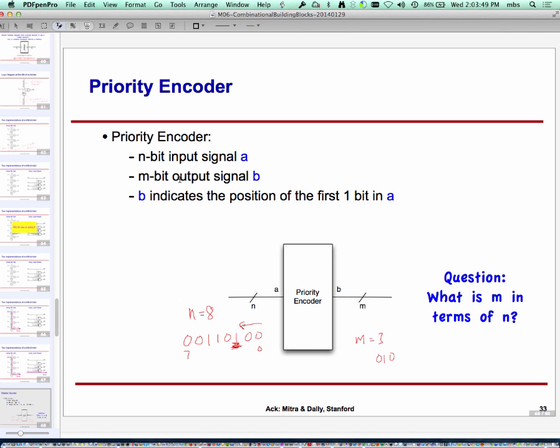Finally, as you think about designing these things, this system really has 6 bits of input, 3 bits of temp and 3 bits of set point, and it has a total of 15 outputs. There is one output which controls the too hot LED, and then there are 7 outputs for each one of the 2 displays. So 7 plus 7 plus 1. Really what we are doing is implementing 15 functions. Of course, some of these functions may share some logic, which is the way you can gain some advantage over what Logisim would otherwise produce.